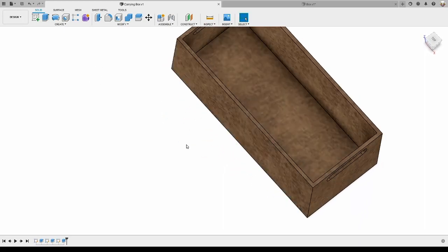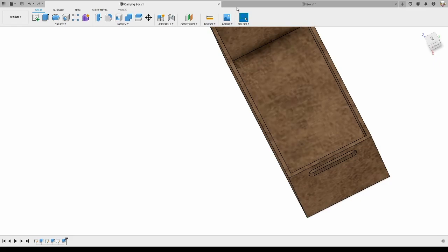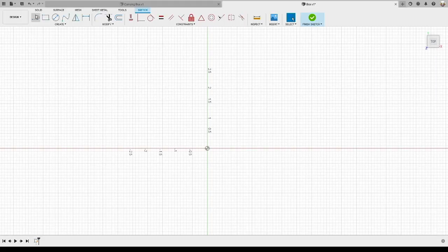What I'm first going to start with is this bottom piece. So in my drawing, my best tool is my rectangle tool. This tool is amazing. You can choose the length and width of it. Say I want it to be 1.5 inches by, let's do 3. You can press tab to go between them. And you can change it later if you change your mind.